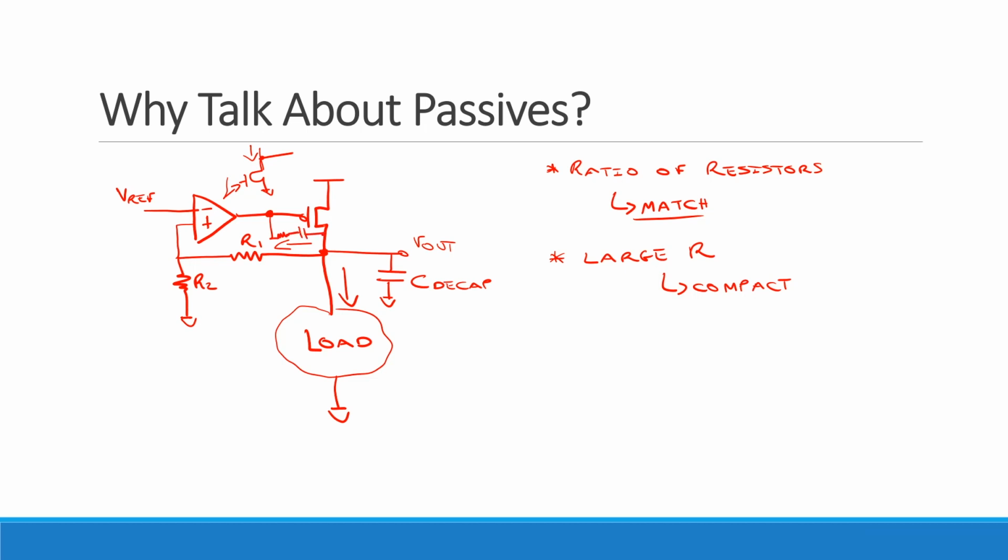Okay, so now again, for those capacitors, or actually for that capacitor, what might I care about? So I care about the ratio of that cap to the load. So again, I care about matching, right? I probably, again, may want something reasonably large in a small area. So again, I sort of care about, in some sense, density, right? There's one other thing here that I claim is sort of interesting that we haven't exactly touched on yet.